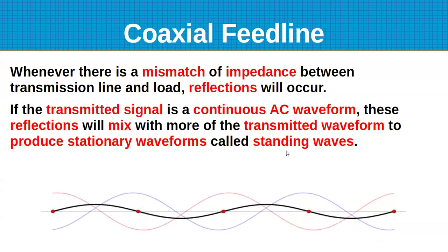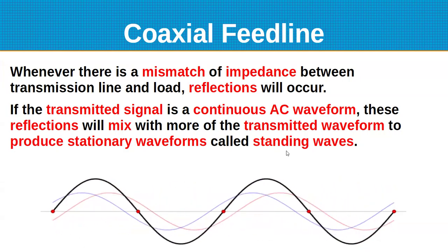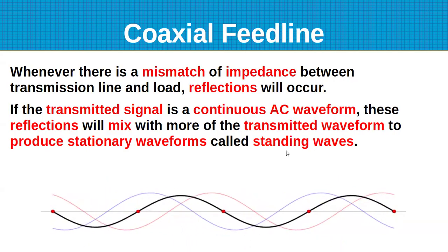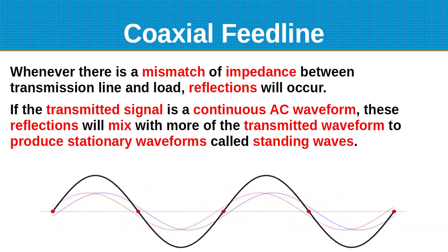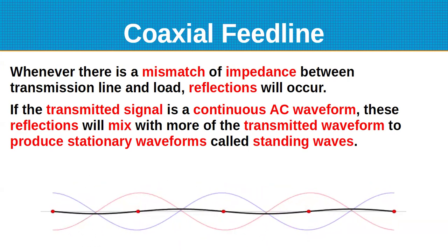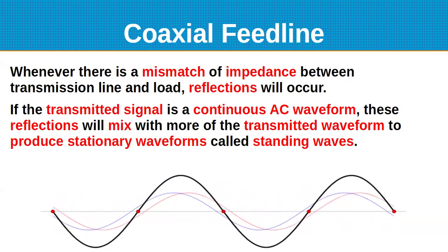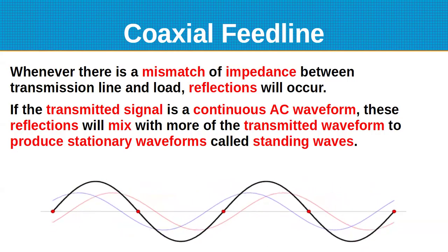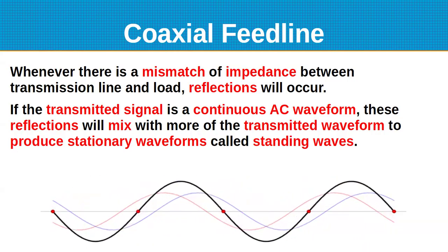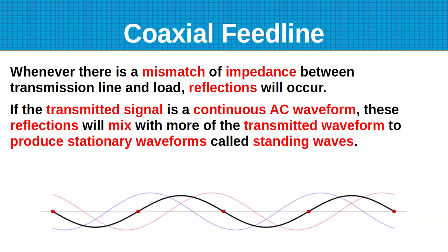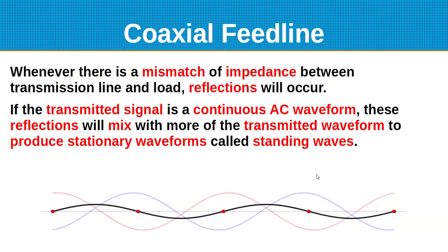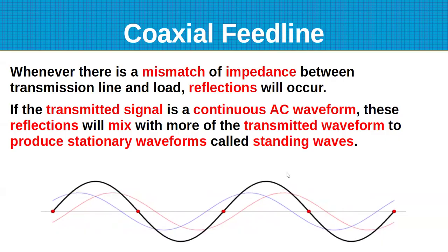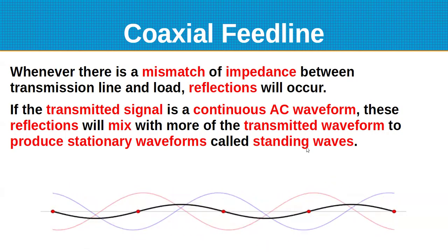Yes. Or, depending on the frequency, for the higher frequencies, you could just loop the coax 3 or 4 or 5 times, which makes a coil or an inductor. And a lot of times that's enough. It depends on the frequency. It's not going to work down at 160 meters unless you coiled, you know, 100 feet of it. But ferrites, or a large ferrite toroid that you wind the coax through 6 or 7 times.